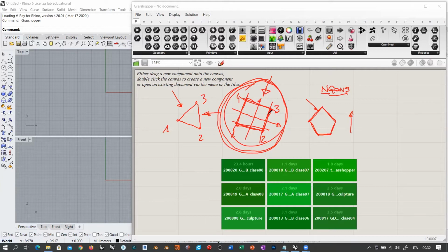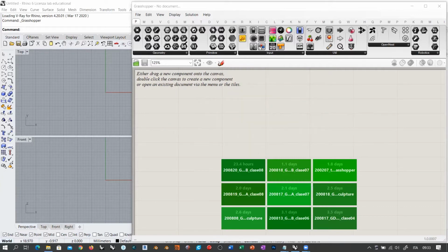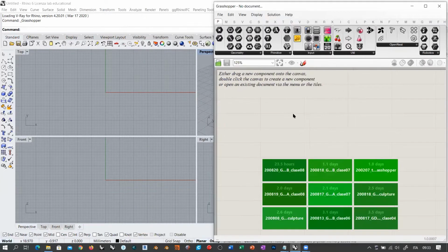This is the reason why we are going to concentrate on quads, and we are going to also look at how we want to implement the mesh based on these quads. Because not everything is horizontal and vertical in our 3D models. So we are going to explain how to bend this kind of mesh topology to our needs. But we will be avoiding triangles and we'll be avoiding n-gons. So we will focus on quads. Now, what I want you to understand, and this was the first step in the course program, is the topology orientations.